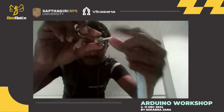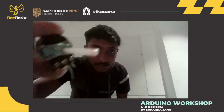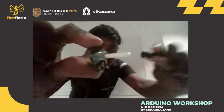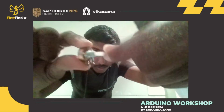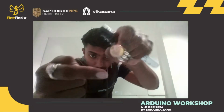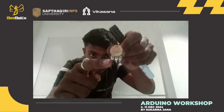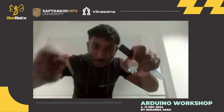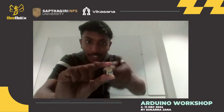This is the potentiometer. Can you see it? This is a potentiometer, which is basically used to change the resistivity. For example, I will be rotating this knob. By rotating this knob, I will be changing the resistivity. There are three terminals here, right? Now terminal 1 and terminal 3 will have a fixed value. The center terminal will keep on changing based on how much I am rotating it.